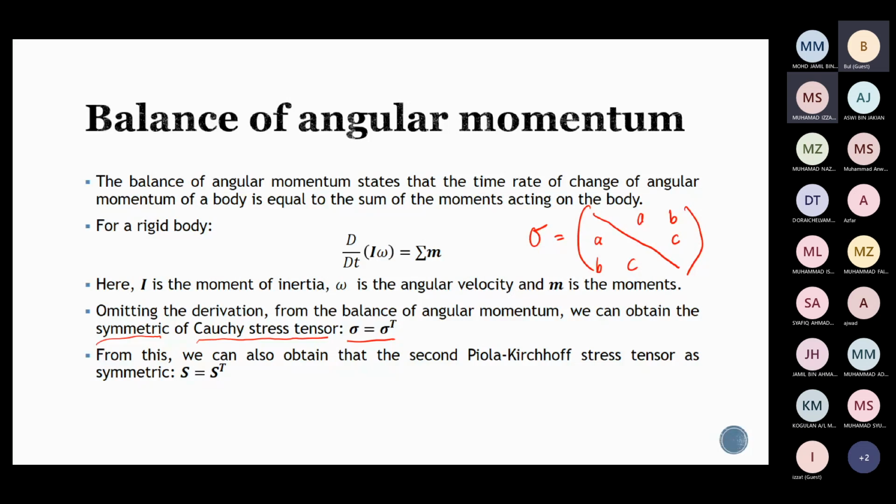Okay, so the stress tensor is always symmetric, and if, let's say, you calculate the stress tensor later and you get a non-symmetric answer, then you know that you are wrong, when you're calculating the stress tensor for Cauchy stress.